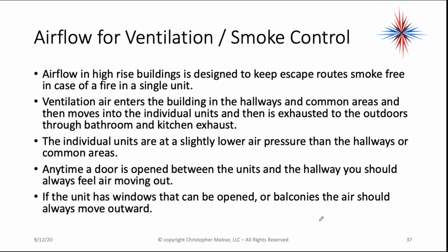The individual units are at a slightly lower air pressure than the hallways or common areas. Anytime a door is open between the units and the hallway, you should always feel air moving out of the hallway into the units. If the unit has windows that can be opened or balconies, air should always move outwards.